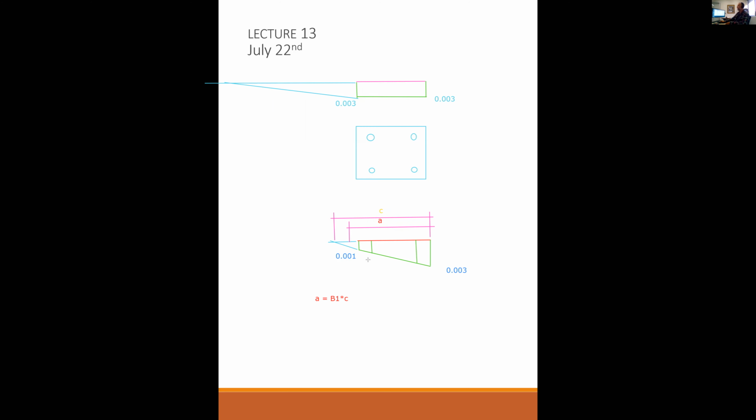So this is the same thing. I'm doing exactly the same thing. It's just that c is not nearly infinite or millions of inches. c is a real number that you can calculate. It's not that big of a number. It's just bigger than the column itself. So this is how you treat little a. Again, if little a is bigger than the available concrete, then you just use the available concrete. If little a is less than the available concrete width, then it's like everything else you've done. You just use a as you calculate it.